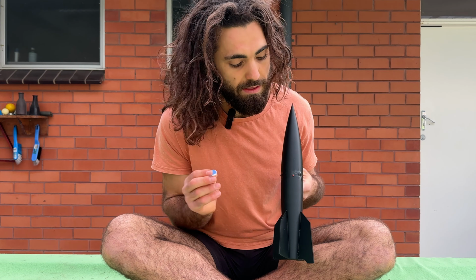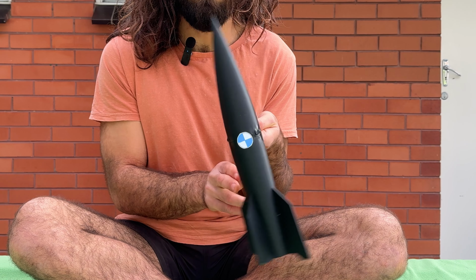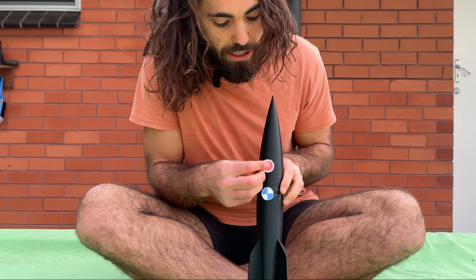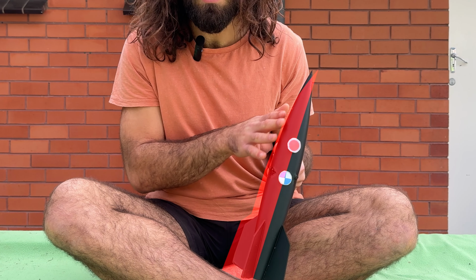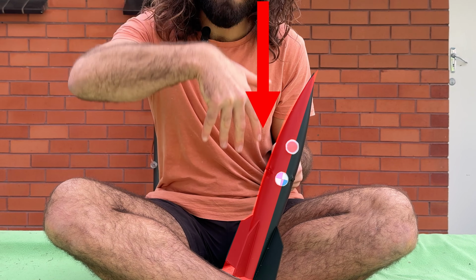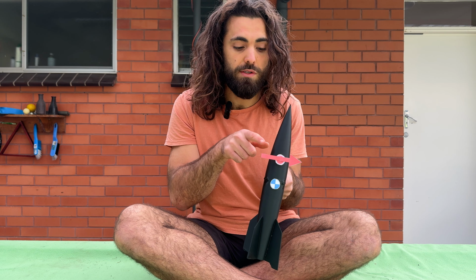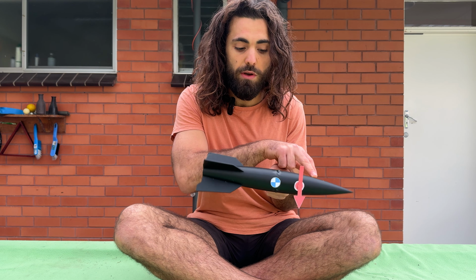Okay, for argument's sake, the center of gravity is going to be somewhere near the center. Let's just say there. And as we said, the rocket always rotates around this point. Now, let's imagine the case where the center of pressure is actually above the center of gravity. And let's imagine there was a gust of wind to the right that just pushed it off a little bit. As you can see, now the left side of the rocket is more exposed to the airflow coming down. So there's going to be a resultant force that's to the right. If we then go ahead and apply this force to the rocket, it's actually going to continue steering off course, which means more surface area is exposed, therefore creating a greater force to the right, and we're going to spin out of control. We say that this rocket is unstable.